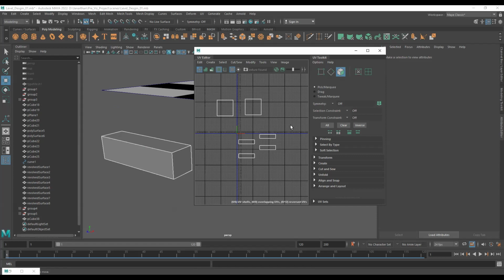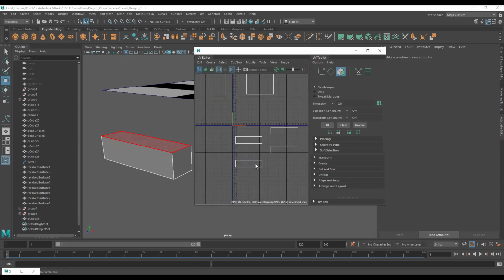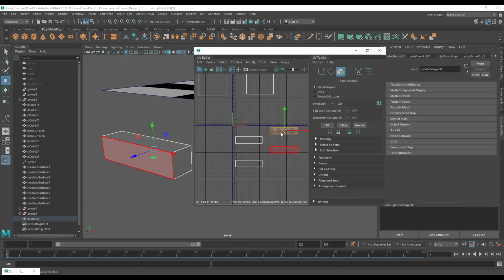Now we need to merge those sides into one particular shell. Now these are all the shells. This is shell 1, 2, 3, and 4, 5, and 6. Six sides of the box. Now the projection is done very well. Now we have to attach these things. So select any one of these edges. You can see the next edge is automatically selected. Select this one, automatically selected.